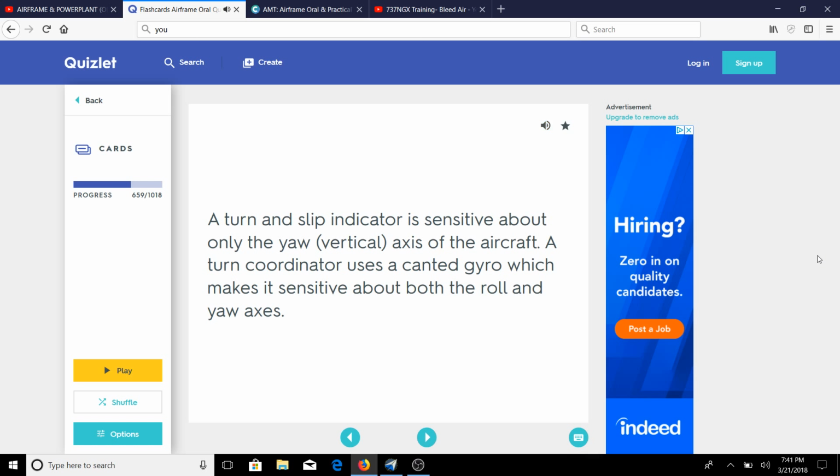Why is a dual tachometer used on a single-engine helicopter? When the needles are married, the clutch is not slipping and the rotor is solidly engaged to the engine. In what units is the tachometer used on a turbine engine calibrated? In percentage of the takeoff RPM.